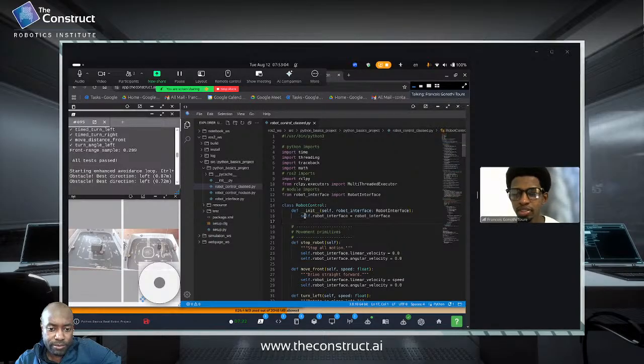Basically here it's initializing and calling this robot interface module. It's saying, okay, we have imported this robot interface in here, and anything that we declare here as self is going to be part of this robot interface module. So it helps us write Python code that calls other ROS robot interface code, which allows us to interact with the robot without writing any ROS program.